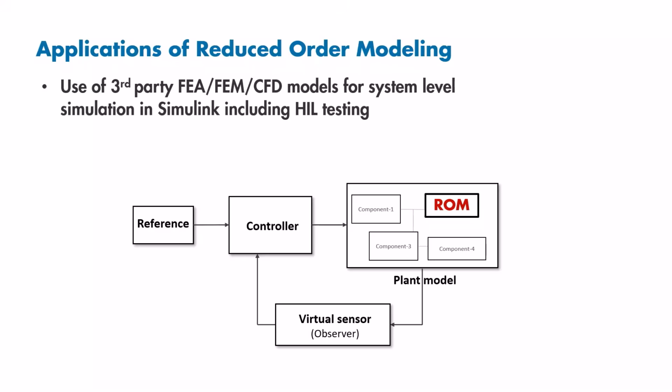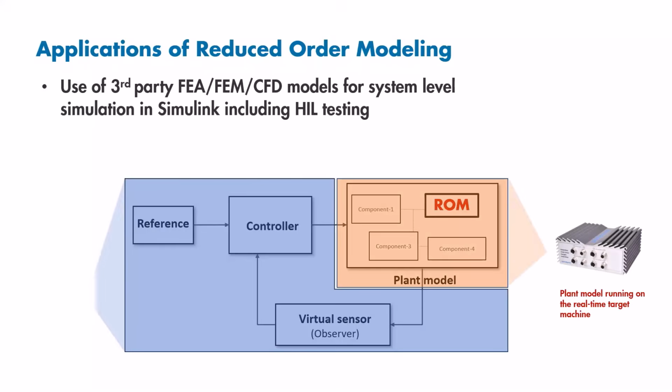ROMs are also useful for hardware-in-the-loop testing, as they allow real-time simulations. Engineers can create ROM representing the physical components of the system, which can run on a real-time machine for testing of the control algorithm on embedded hardware.